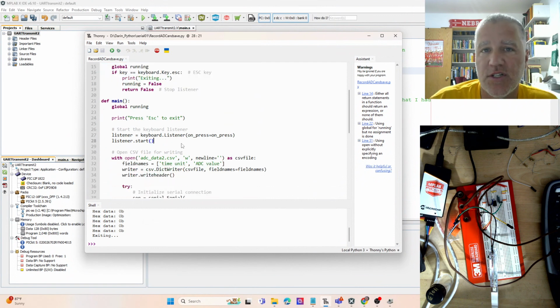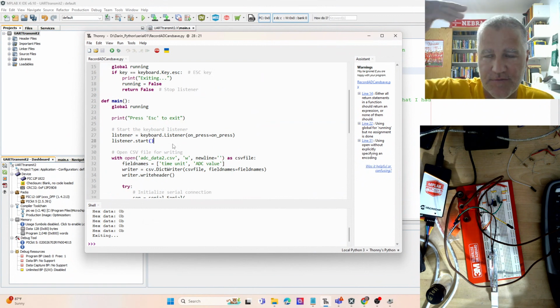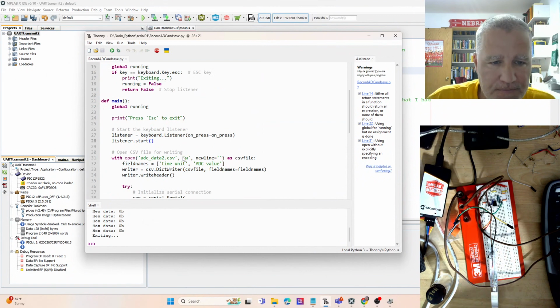Here is very much like the previous program. We're just going to get the information that's coming from the microcontroller. Now, instead of just being a single number every time, it's going to be whatever value was from the A to D, then got pushed into the T-reg, and then out into the computer.